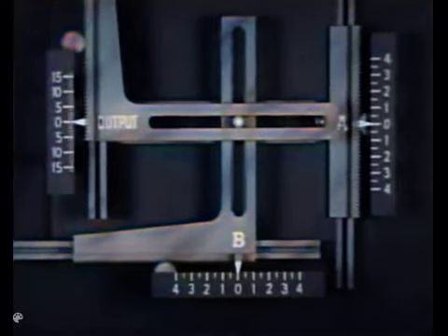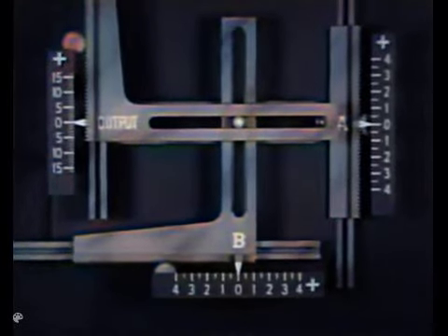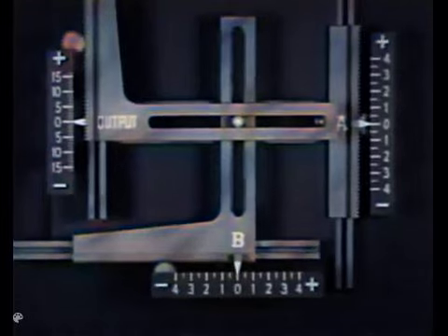When the multiplier pin is lined up with the stationary pin, both input racks and the output rack are in zero position. To make it easier to see how this mechanism operates, let's put appropriate scales along each input rack and along the output rack. The values are plus in one direction and minus in the other direction.